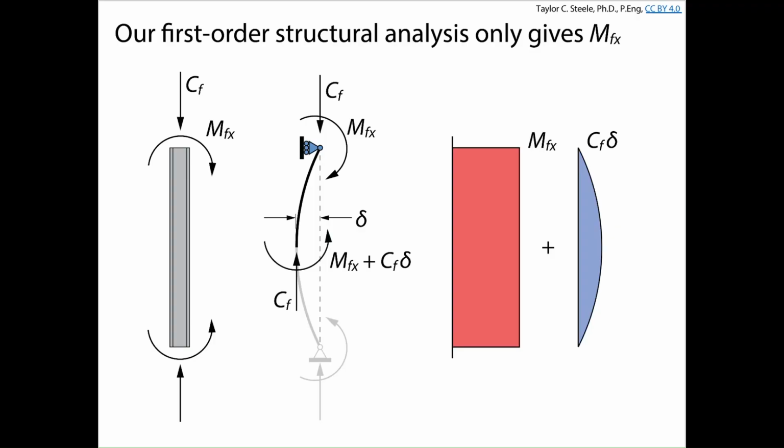One other thing that's different between beam columns and members that carry combined tension and bending: if we didn't have any axial force at all, let's just pay attention to the moment on this beam. Let's assume it's a constant moment. Why not? If we have a beam with a constant moment, it's going to bend, right? And so if the beam is going to bend, then it's going to have a certain displacement. We'll call that maximum displacement here, delta. That's the mid-span deflection caused by just having a uniform moment acting on that beam.